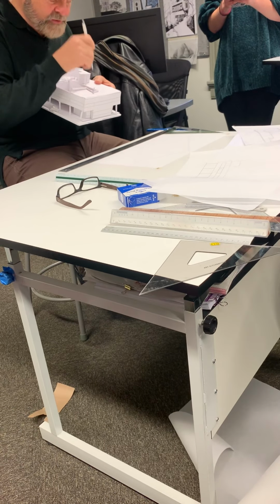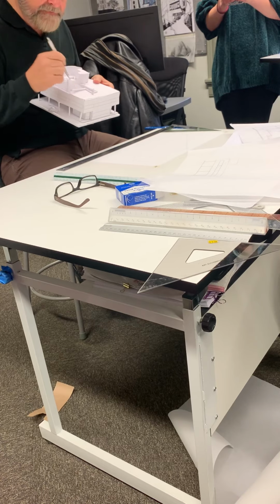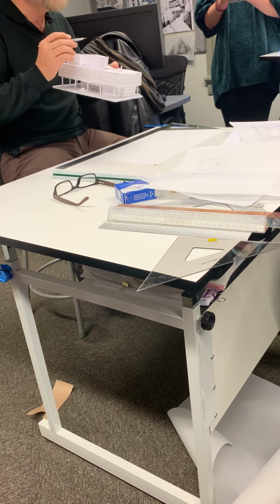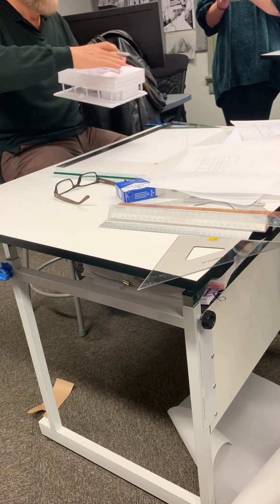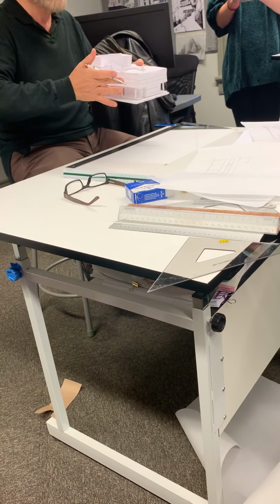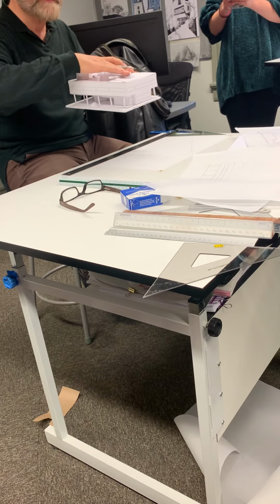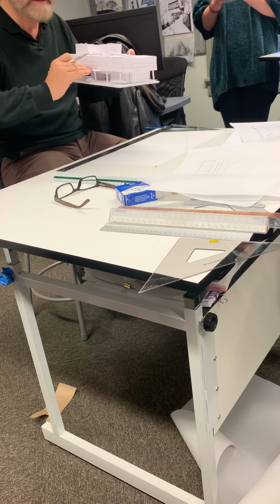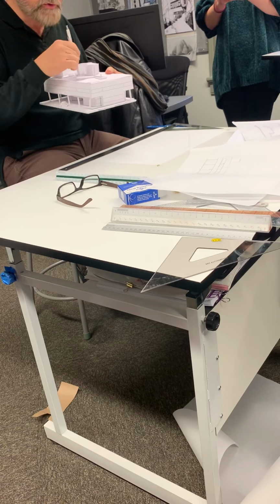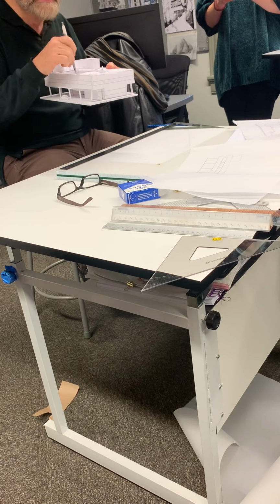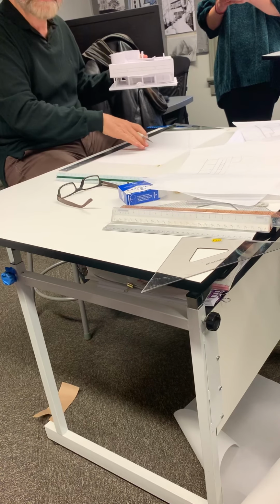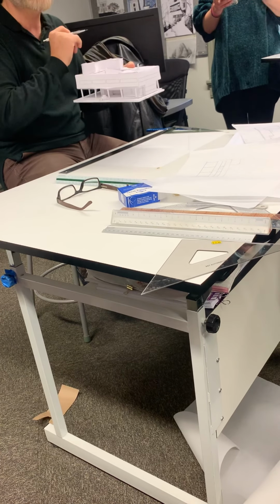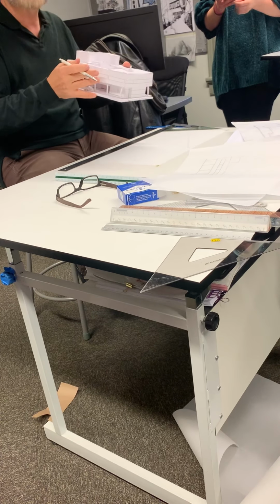And then you need to be able to carry them all the way down and find where this new plane is, right? And remember, the first thing you need to do is find out where the big volume is, then the top surface, then the subtraction of the top surface, which gives me the next surface. Because when you start drawing this stuff, it needs to be dimensioned from where that surface is. And then this stuff needs to be dimensioned from where this surface is. You can't just do it like this, okay?